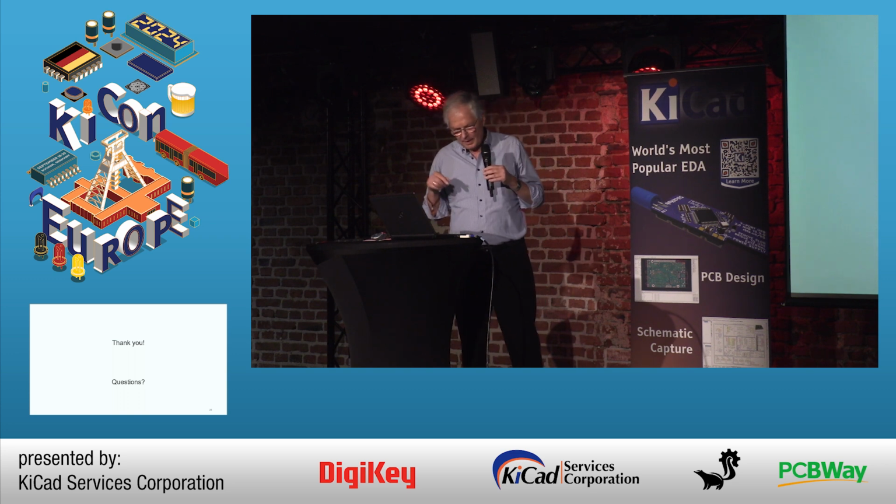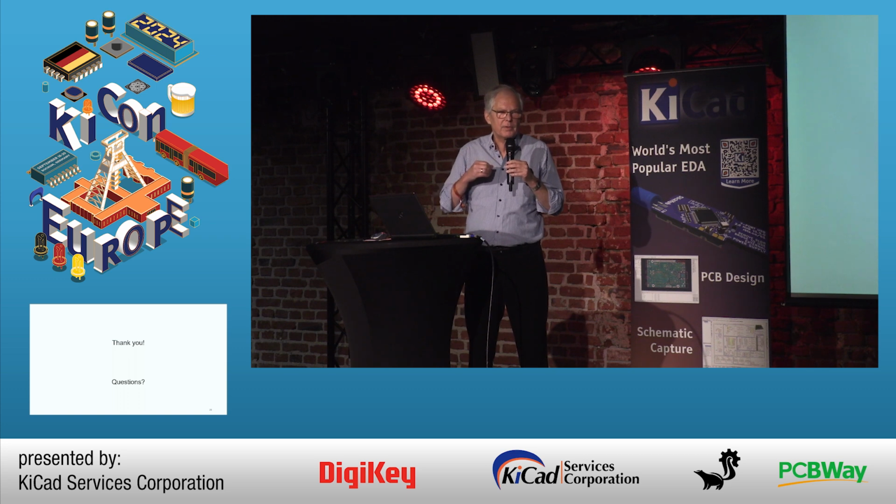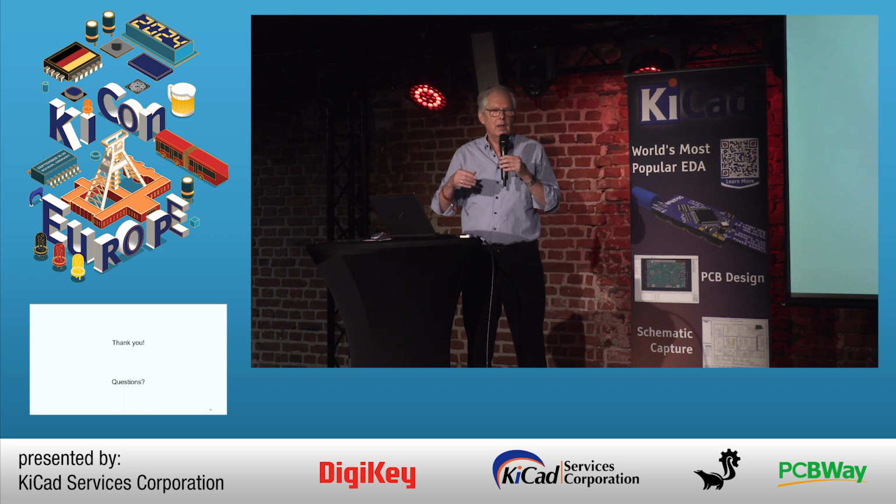There is something integrated already into Eeschema. These are so-called IBIS signal integrity checks. The vendors offer IBIS models. These are interface models, not models for the whole MCU, but for the output or the input. Then you can check if you send a signal, will it be the right signal at the receiver? But still, what is missing is what is in between. How do we calculate this?